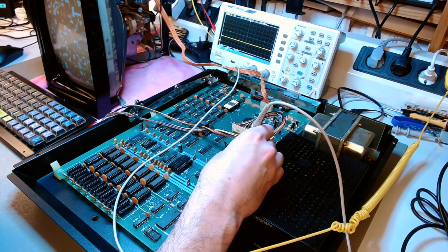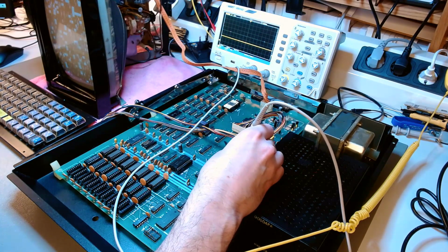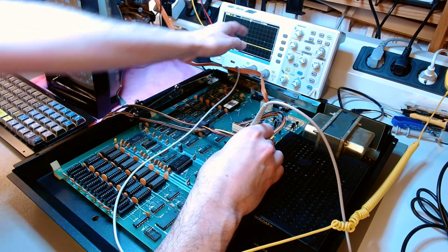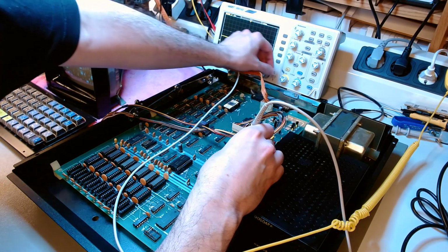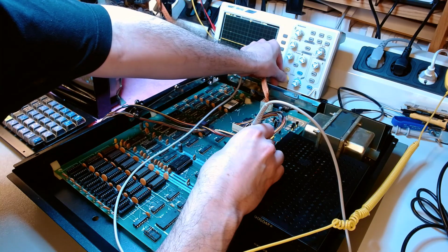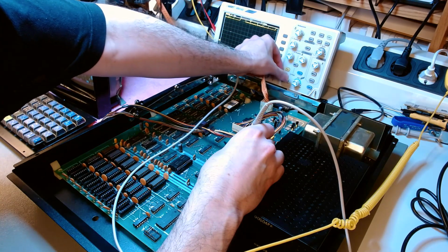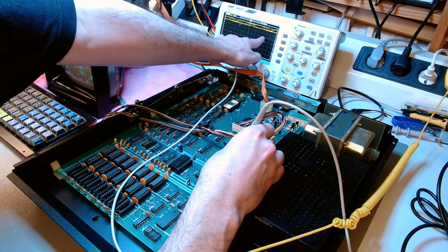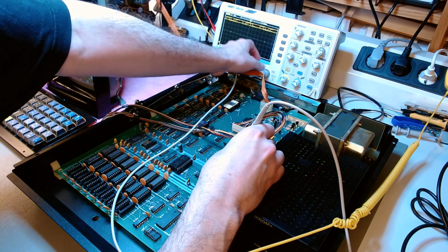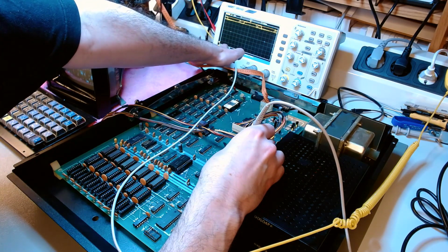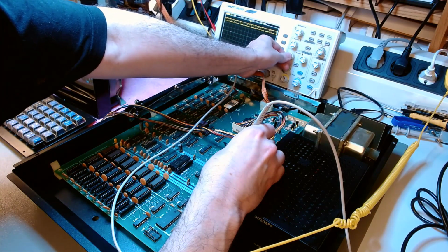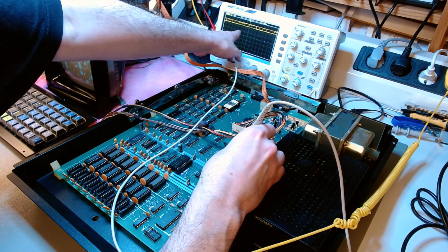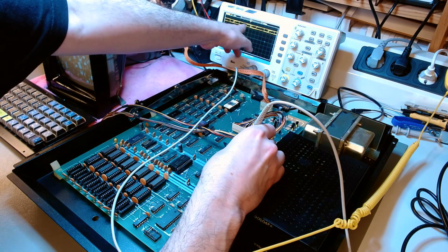So the CPU is not trying to drive the address bus, and it's the only thing that drives the address bus in a node system like this without DMA peripherals and all that stuff. So the CPU is not even trying to read the ROM to fetch instructions to execute. It seems to be dead. So the lines are floating, and I zoomed in into those levels, and you see that interference there. That's characteristic of a floating line. What we are picking up on that line is noise from the other lines that are switching within the CPU. So the CPU is not driving the address bus, which suggests that the CPU is sort of dead.